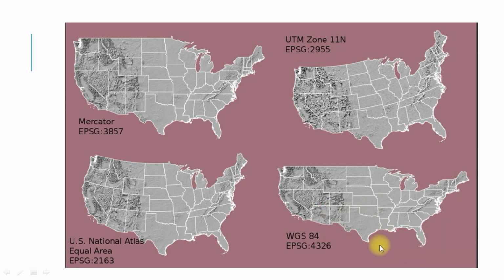So it depends on the goal of your projection. It depends what type of projection you choose. For instance, if you want to measure the distance between two points, two cities, accurately, you should choose the equidistant type of projection to preserve the distance between points. But if you are going to calculate the exact area of countries or regions, you should always choose the equal area type of projection.